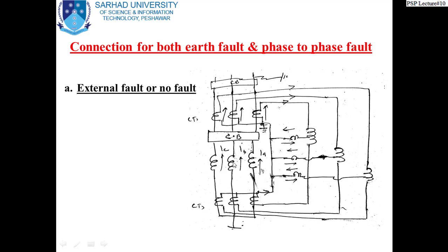So we have installed a CT on each phase, one incoming and one outgoing. A differential scheme has been shown here in this diagram.